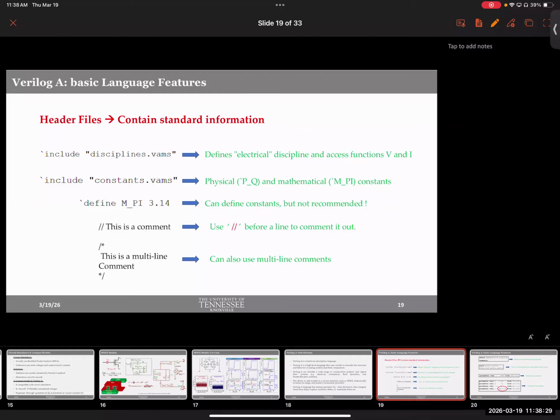You don't have to make a model of huge complexity, but every once in a while in your career, you might want to create a model for something simple. So that is definitely on the table, using a Verilog-A model, but not making the model from scratch. But typically that also helps, especially if you open up a model. How do you handle parameters? How do you change the model and update the model for your benefit? That is often handy. Oftentimes we get models for free from other groups, and then we update those models to add features or to repurpose them for some other devices that come in the future. So if you can understand the syntax, if you can understand the approach towards modeling, it is easier for you to make those tweaks rather than make something from scratch.